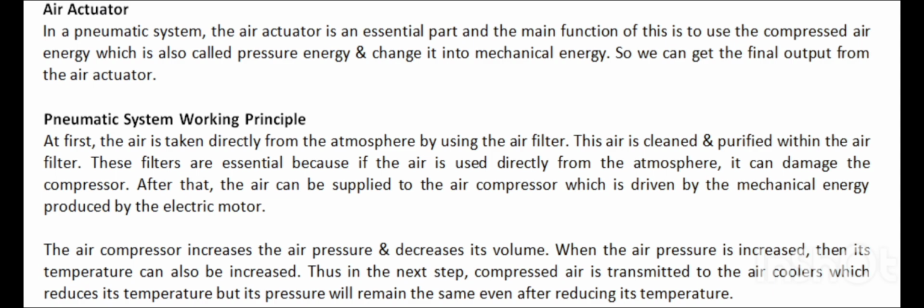After that, the air is supplied to the air compressor, which is driven by the mechanical energy produced by the electric motor. Air compressor increases the air pressure and decreases its volume. When the air pressure increases, then its temperature also increases. Thus, in the next step, compressed air is transmitted to the air cooler, which reduces its temperature, but its pressure will remain the same even after reducing its temperature.